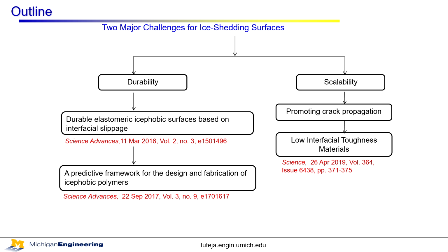with the whole idea of, okay, I need to reduce the ice adhesion strength. There have been many different approaches, from waxing of various surfaces to prevent adhesion of ice and snow. People may have used waxing on their skis to make them go faster. So wax is a good way of preventing the adhesion of ice and snow. But the challenge is it's very temporary, so there's no durability associated with it.